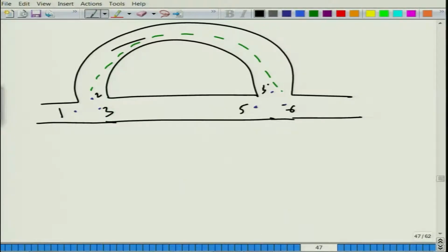And as I briefly talked about in the last few lectures of week 9, this impedance matrix is a beautiful concept, because we do not have a constraint that the system should have only an even number of ports. It is not necessary that you have a muffler system with only 2 ports, you can have 3 ports also. In such a case, impedance matrix is very useful for characterizing the system, and then we can do some network analysis, which anyways we are going to do now. So, for a simple 2 port system, and then we will consider another test case.